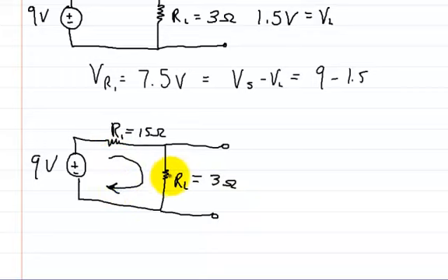That's how you would solve this problem, and that's how, if you wanted to charge your cell phone using a 9-volt battery and you wanted to make a voltage divider in order to do it, that's how you do it. Oh, by the way, I don't really recommend you actually do this to charge your cell phone. You'd want to add some other components in here to make sure that things don't surge, in case the battery gets too hot, stuff like that, because that'll change the resistance and a few other things. But that's for later stuff.